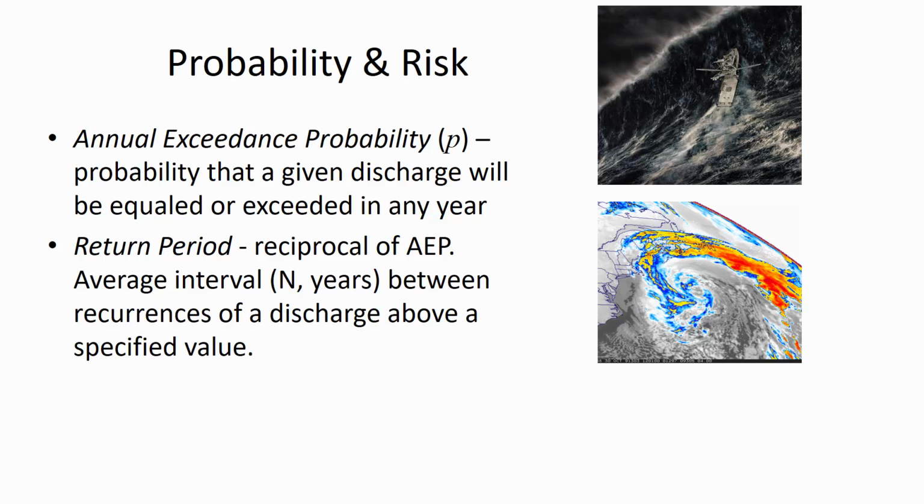You've probably heard the phrase the 100-year storm before. Now, a lot of people say that the storms that hit West Virginia last summer were larger than the 100-year storm. And so, on average, a 100-year storm has an annual exceedance probability of 1%. And so that means that, on average, in a given year, we should only have a 1% chance of the 100-year storm.